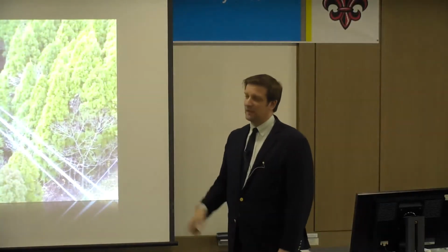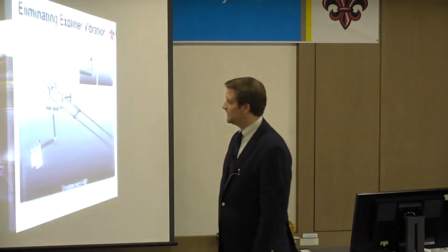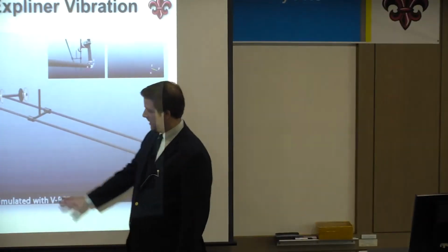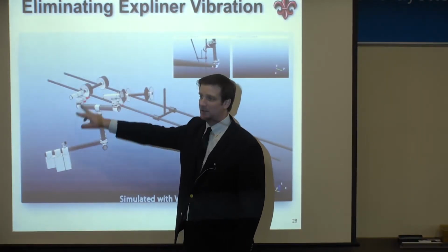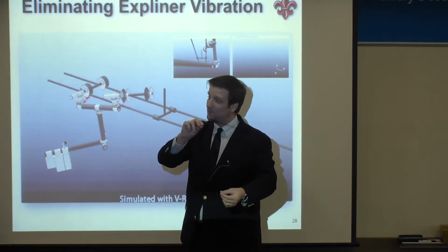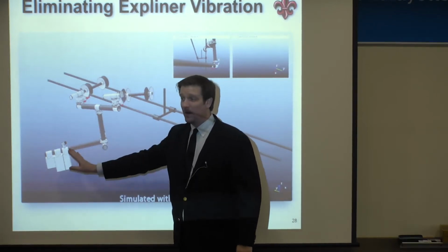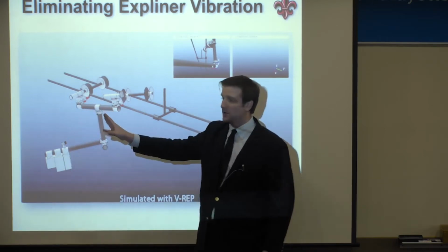What you might have noticed from that video is they cut out some frames. They cut them out because when it's in this mode, where the center of mass is back there and it's only on two pulleys, it's really easy for this system to start rocking. If you have some wind blowing, or even just driving in this kind of acrobatic mode, it will cause this system to rock.